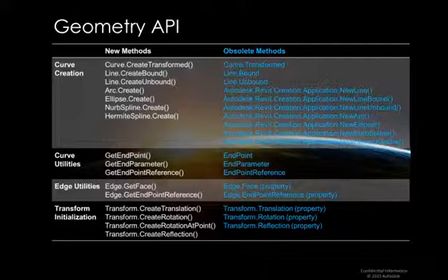Another aspect that is cleaned up by these changes is the differing behavior of certain properties, such as endpoint, which is declared to be a property, but it still takes an argument to specify whether it's the start or end point. In Visual Basic, this remains a property, whereas in the generated C# API, a lowercase get underscore was prefixed to the property name. By converting this property to a method in Revit 2014, this kind of ambiguous behavior is removed.